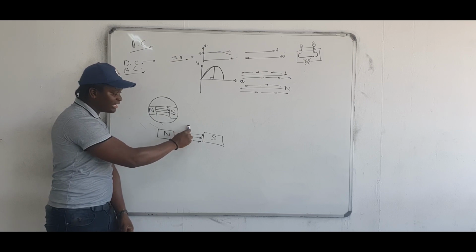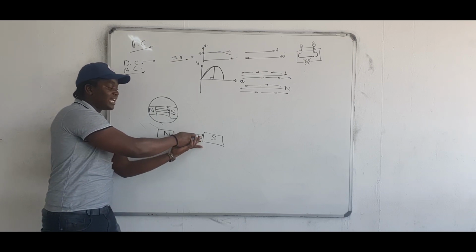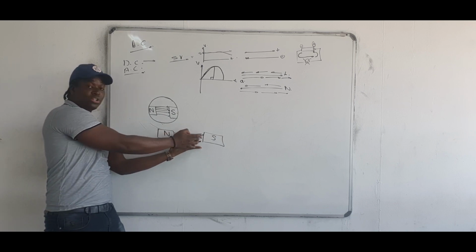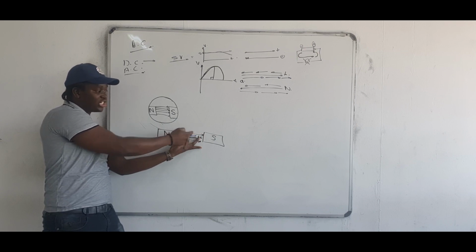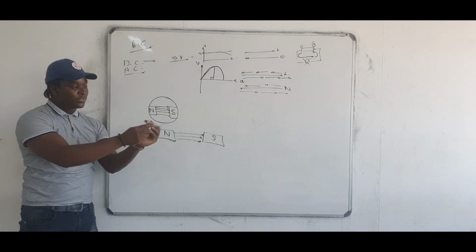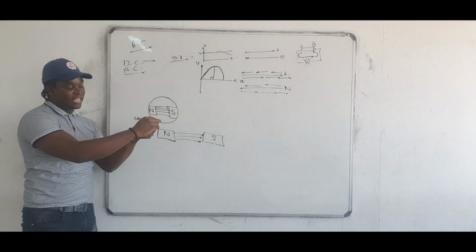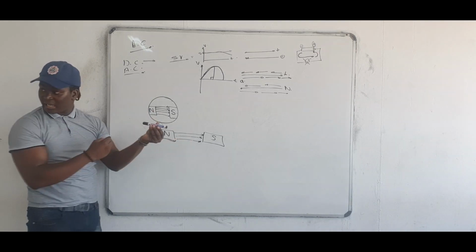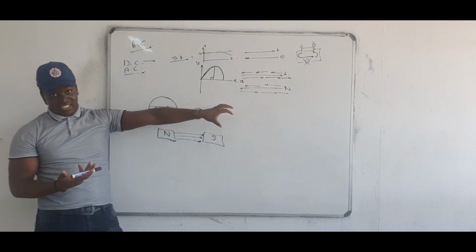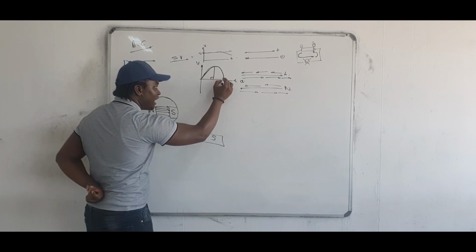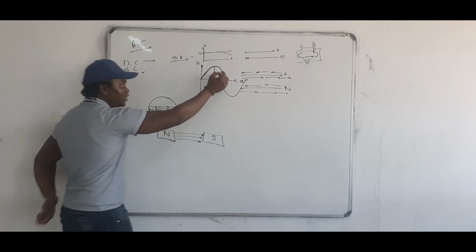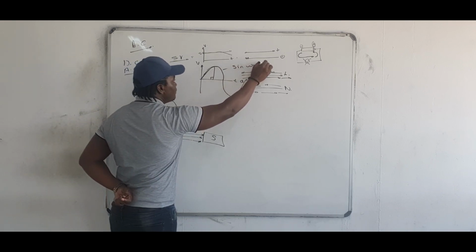And if it does a full rotation, now check what's aligning with the magnetic flux. The current is now induced from the cap to the butt. That means it has reversed the direction inside the wire itself. So if it was traveling like this at the beginning, then after a full 180, it's now traveling like this. But if it changes direction, we call that a negative value. So our current now does the exact same thing, but on the negative side. This is known as your sine wave.